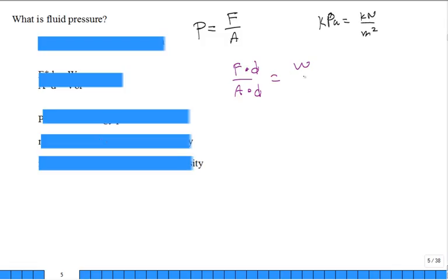So you can see that the pressure is not only a force per unit area, but when I multiply it by 1, distance over distance, distance in the numerator, distance in the denominator, I pick up work, which is going to be some sort of increasing or decreasing mechanical energy, depending if the fluid's doing work or receiving work.